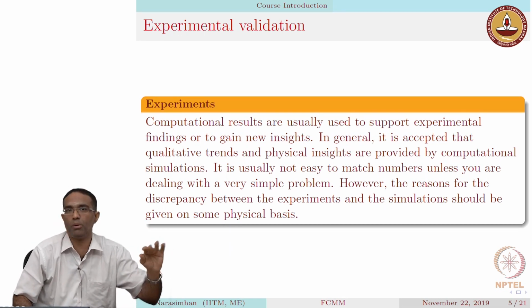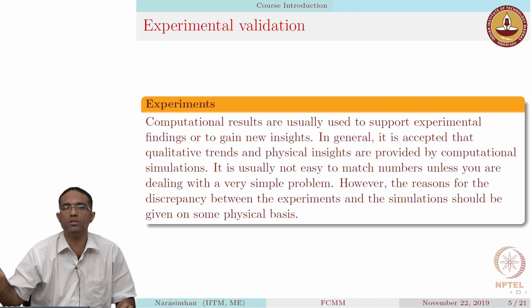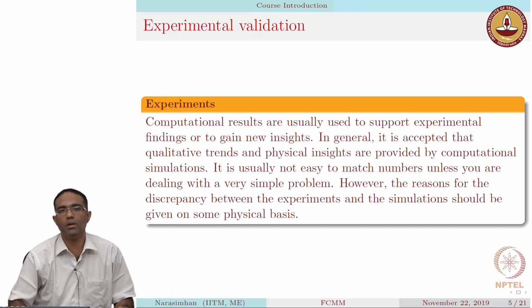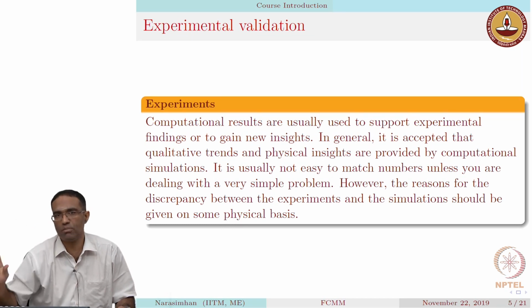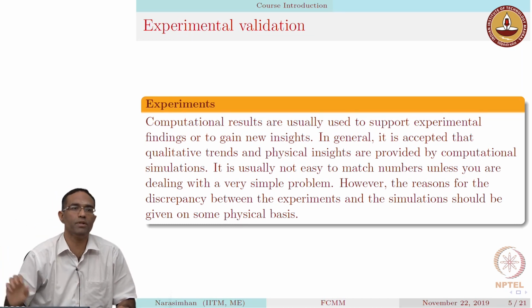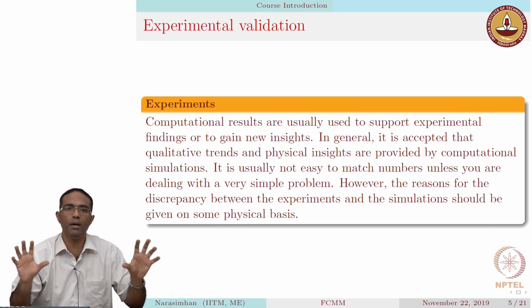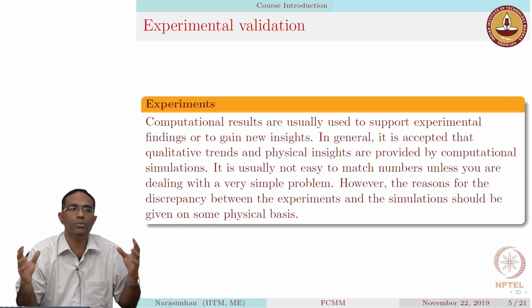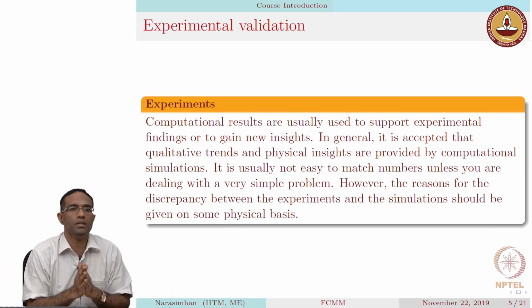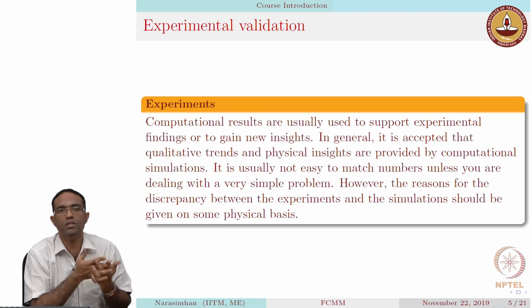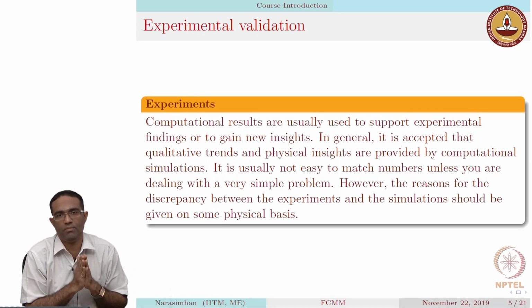A single crystal is probably a little bit stronger than the polycrystal, and the specimen that you are using in your laboratory probably has a large number of defects, and these are not the kind of defects that you have simulated explicitly on the computer. So you need to be able to draw some logical conclusions based on which you will be able to say that the computational value that I got for my Young's modulus or the yield strength is actually not too bad.